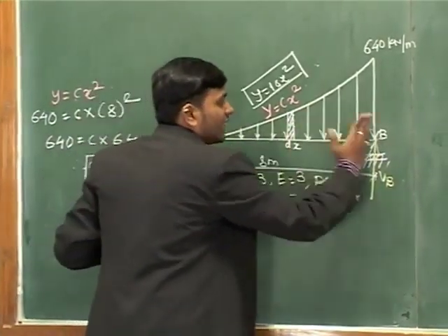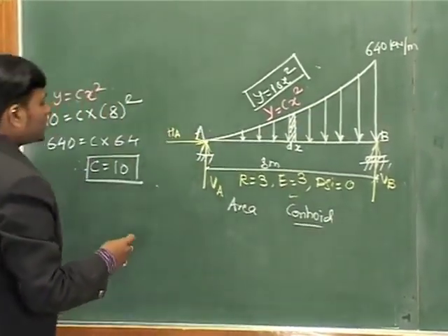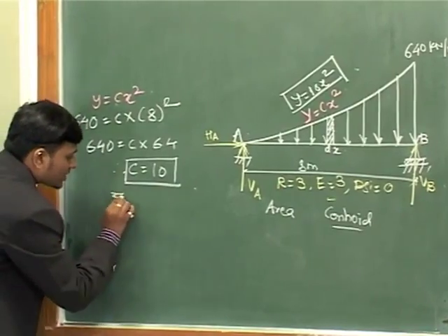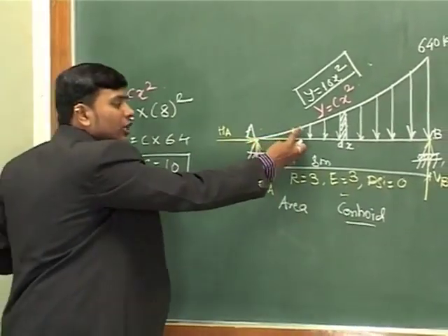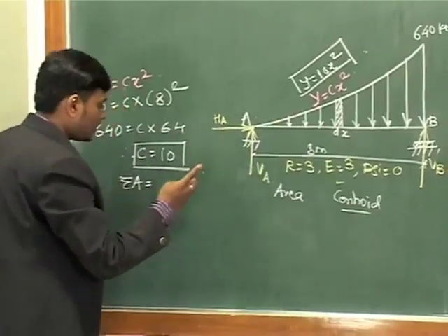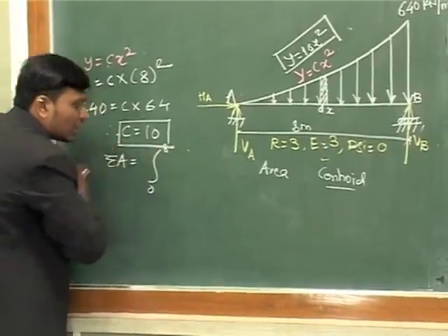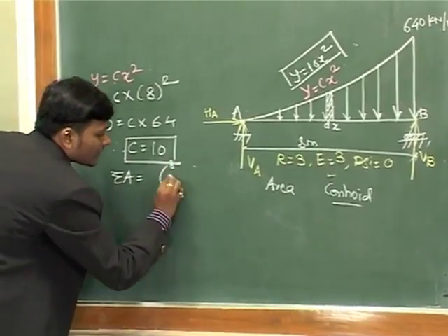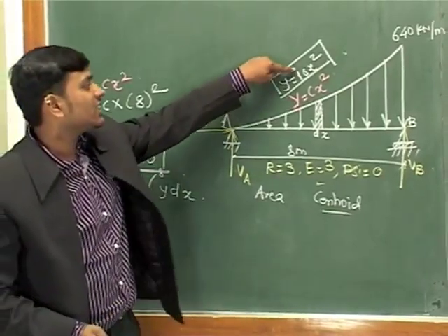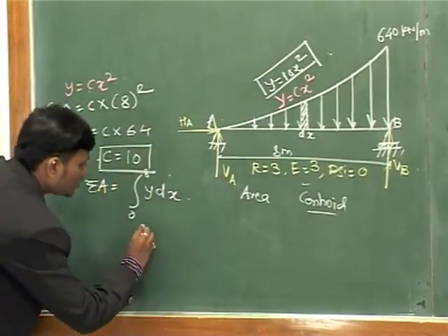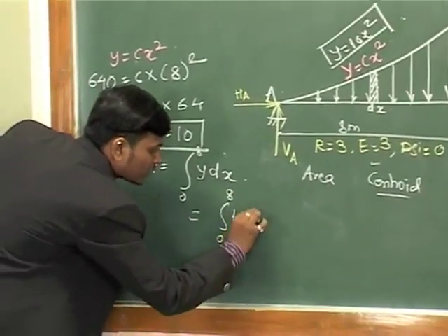The area is the magnitude of force when you convert this load into a point load: the integration from 0 to 8 of y dx, where y is 10x square.